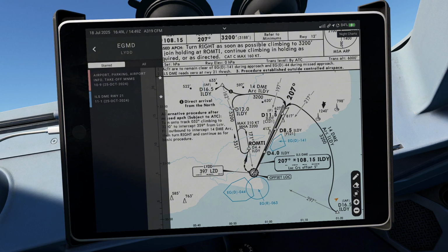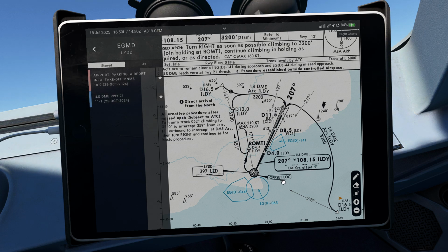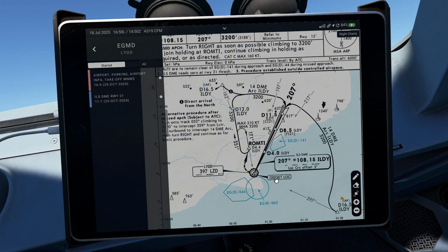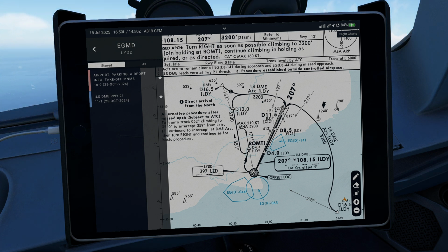It means the United Kingdom AIP and Jeppesen chart will usually include a caution, like the localizer is offset 5 degrees, which you see here, and also within a bracket here. The offset localizer is notified in both places, and this approach also requires visual alignment with the runway before landing. Autopilot guidance may not align the aircraft with the runway centerline.